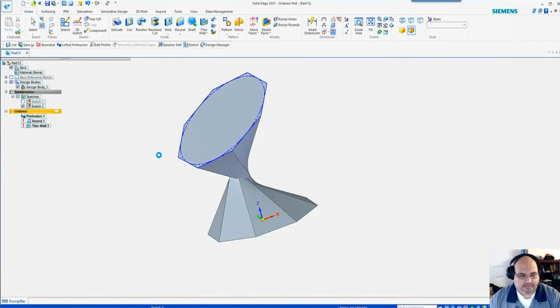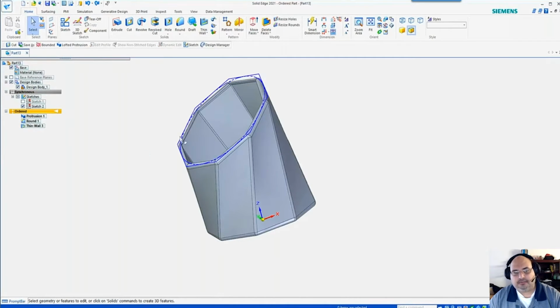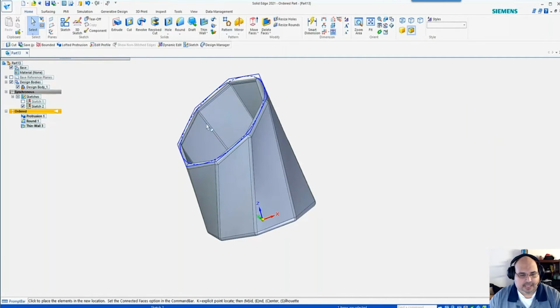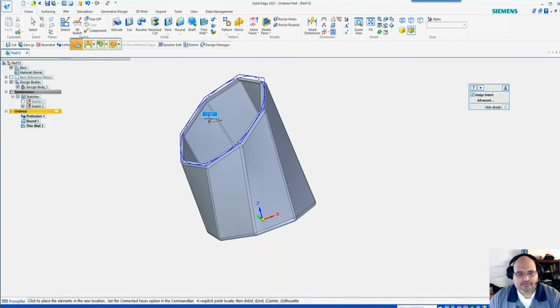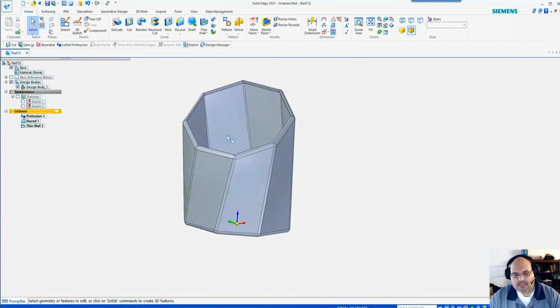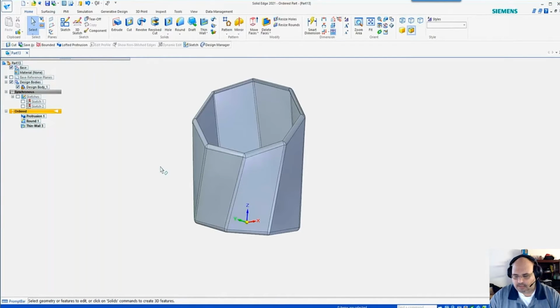And you can see there, they complete. So Control Z is your best friend here. There's that undo, as long as I don't save or go to another tab. As long as I have that undo, I can still edit and manipulate that model. But that gives me an extra layer of freedom on my model. By having those two simple sketches over here in the synchronous side, it allows me some freedom and the ability to be a little more creative when I go in and start blending the two environments together.